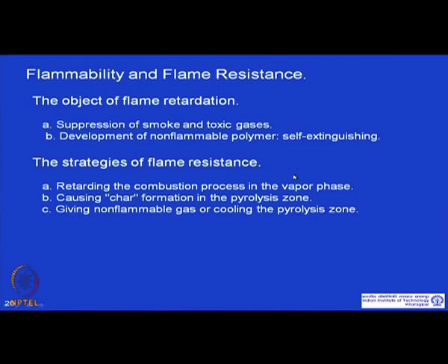So, the strategies for flame resistance are to retard the combustion process in the vapor phase, and char formation. If you have a polymer which forms a high level of char, typically halogen containing polymers and also inorganic polymers, and sometimes added additives, for example ceramic additives, which do not burn and just stay in the system, they contribute to char formation.